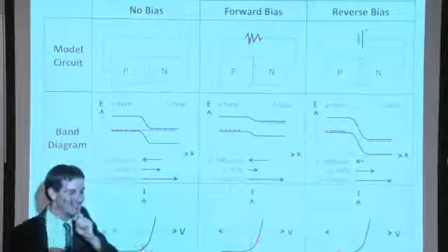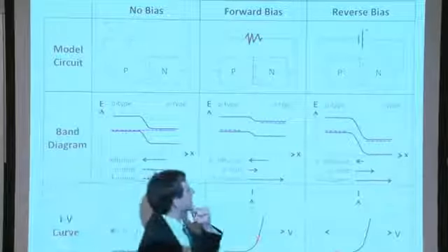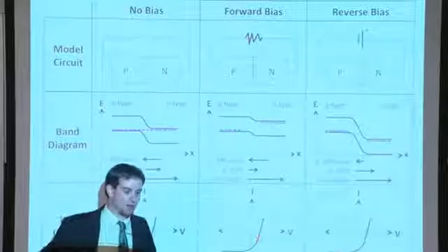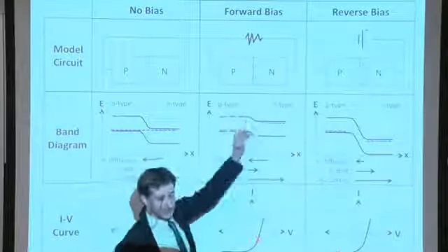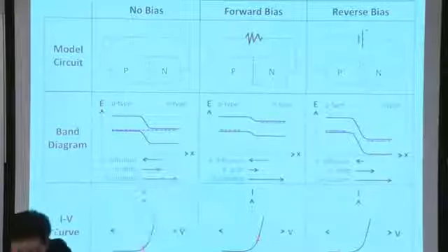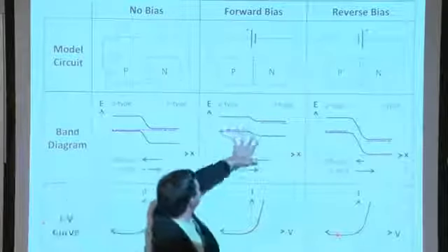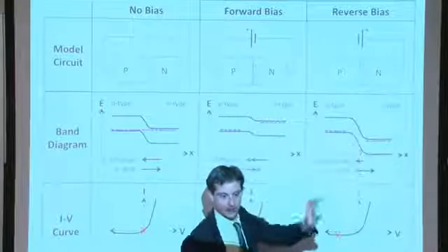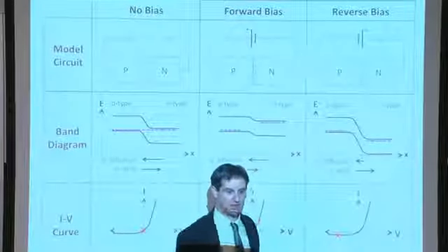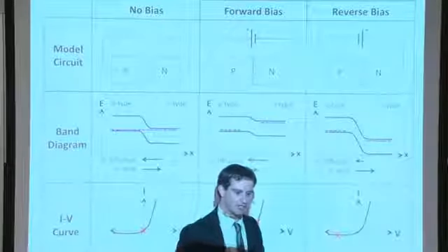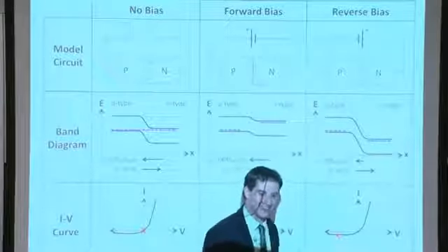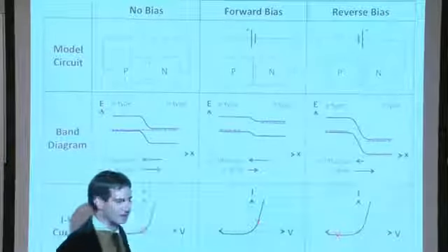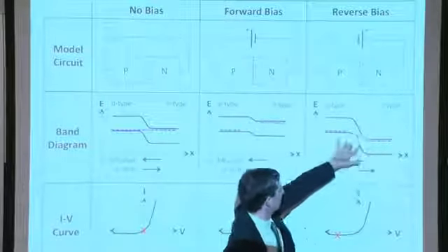So then can the sun ever reverse bias? No, that would be very difficult. What you could do, though, is have a bunch of solar cells connected in series with this one that are producing forward power. You could shade this device, and then power could be flowing backward through it. In other words, it could be in the dark, in a reverse bias condition just because of the way the other solar cells around it are behaving. If you have a shaded solar cell in a module, for example, imagine a seagull lands and covers up one of the cells, that will be under reverse bias, and that could present problems if the solar cell can't withstand the reverse bias.